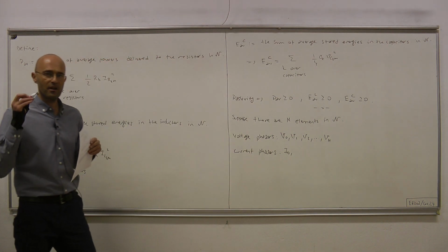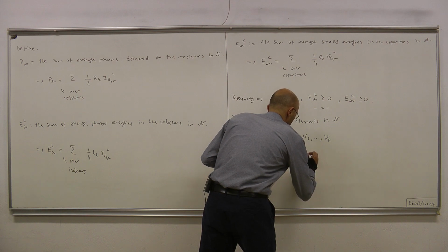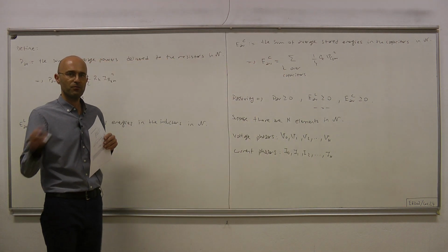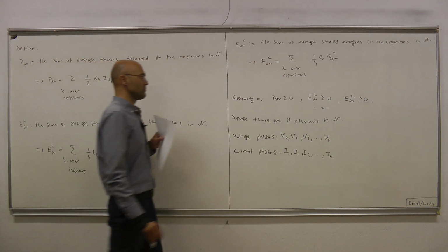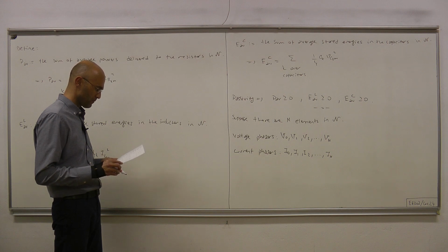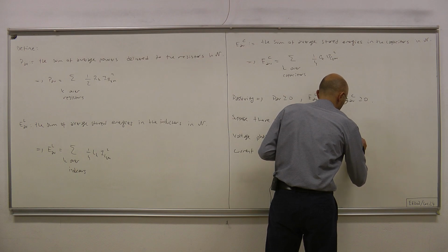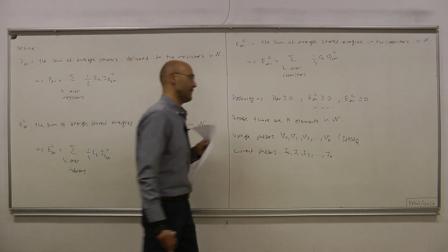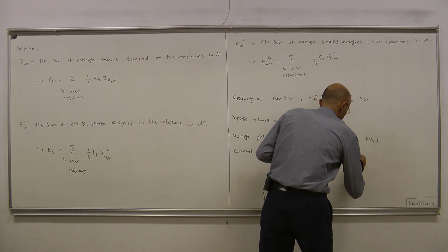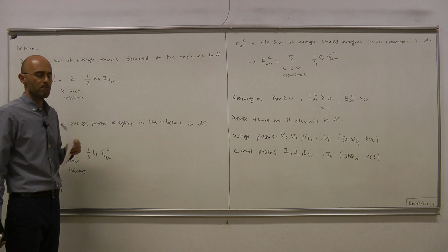Again, I0 is the current at the port terminal, and then we have I1, I2 up to In, the currents corresponding to the elements inside N, namely resistors, capacitors, and inductors. Now we know that the phasors of voltages satisfy KVL, and the dual statement holds true for the currents, namely the currents satisfy KCL.